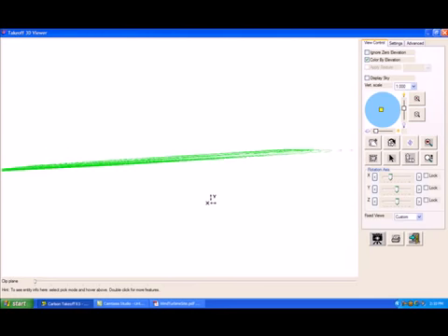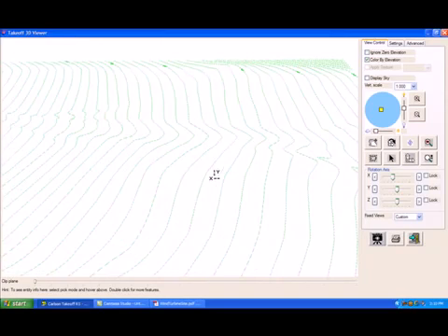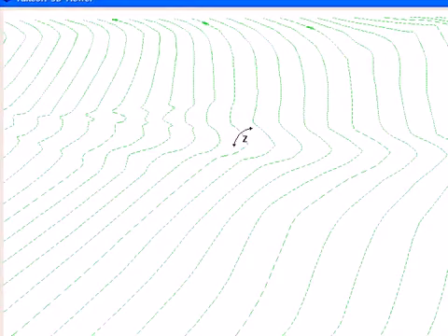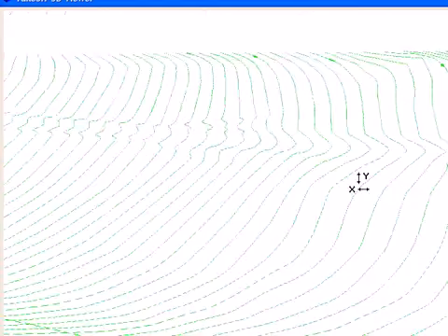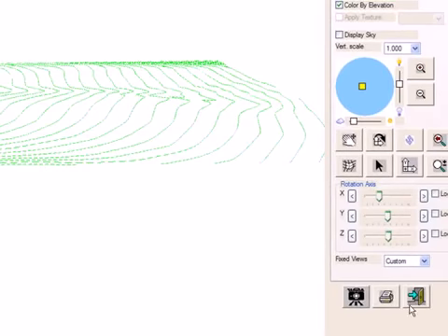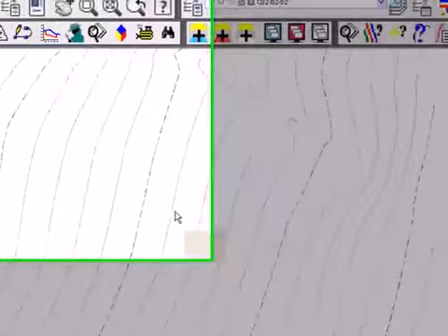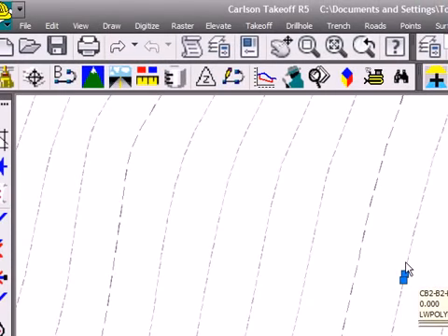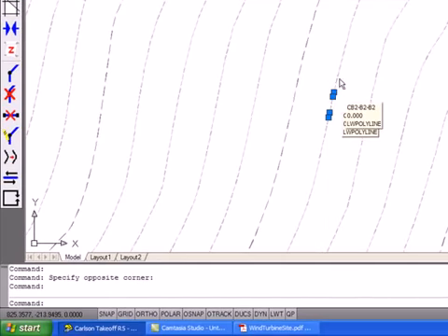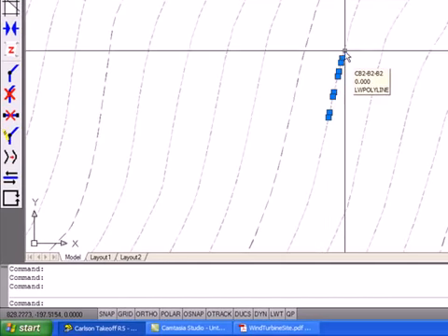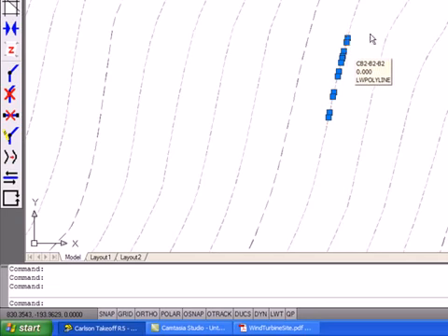This site is completely flat. Okay, so working off a PDF, elevations don't come through from the PDF, so I'm going to have to elevate this line work. The problem right now is that each little dash is its own line. So if I wanted to change the elevations, I would have to change the elevation on each dash line.